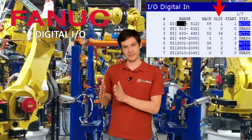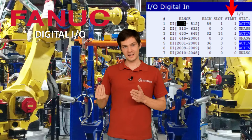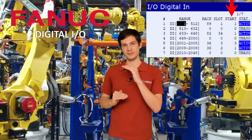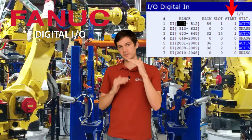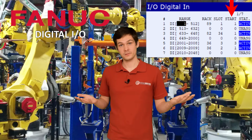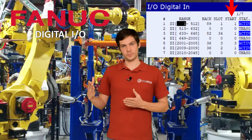The last thing over there is the start number. What is the start number? So basically, this is the number that you want to start your communication with. So for example, we have the PLC that has 512 bits that you communicate with, right? But for any reason, the first 256 you don't want to use, okay? Or you want to switch them, like the first to go to the back, kind of a byte swap. So that's where the start point comes in.